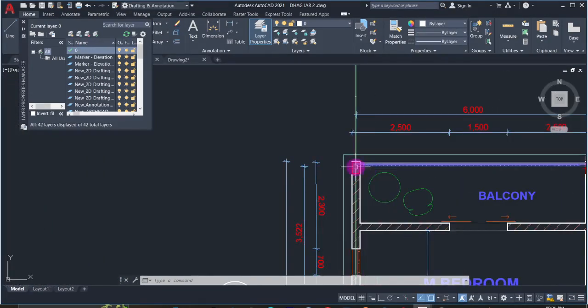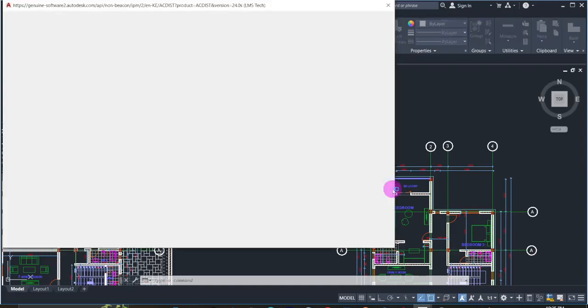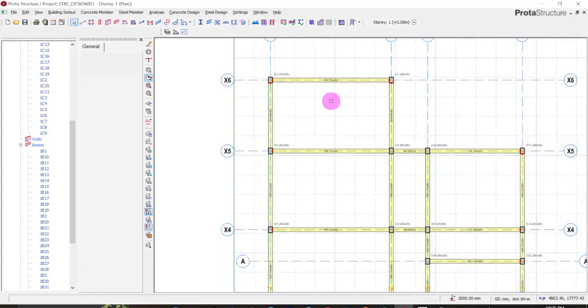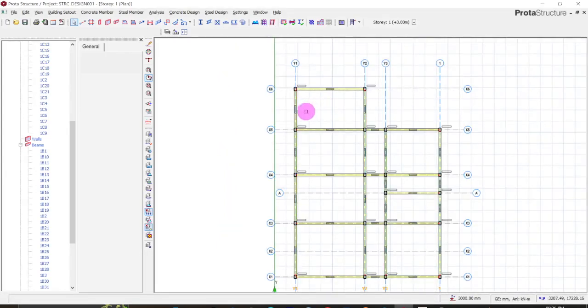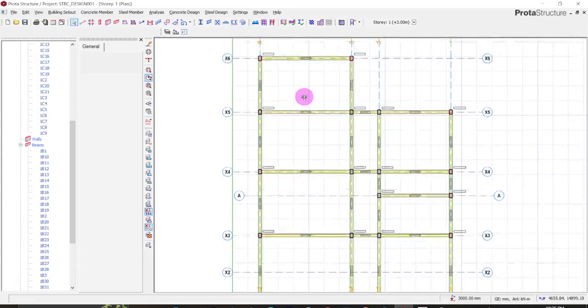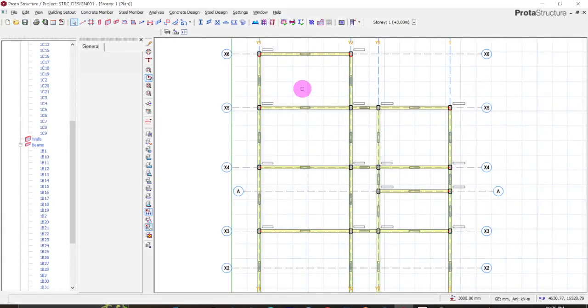I was just thinking that we should bring these columns to here and then introduce a cantilever below on this side. So that would mean this is the upper floor, isn't it? There's a wall. So I was thinking that you could introduce a cantilever here. Or I think it's better we leave it that way, because there's a wall beneath.